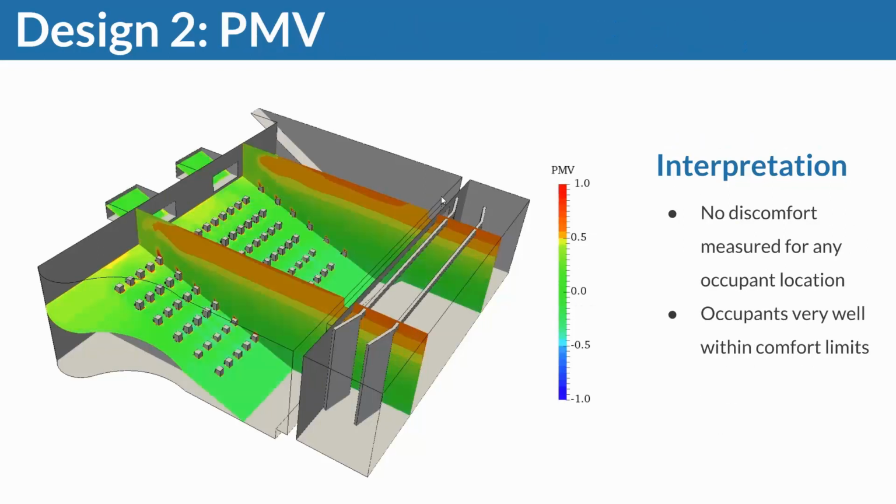Now, what we're here for, let's take a look at PMV, and that's a view we like, right? We can see that nearly, or actually all our occupants are in a green region, right? So above -0.5 and below 0.5. I mean, here it's getting close. Let's take a look, right? I mean, here it's getting close because this is, again, where we have the outlets where most of the used and already warmed air is streaming out. But still, looks like we're good PMV-wise.